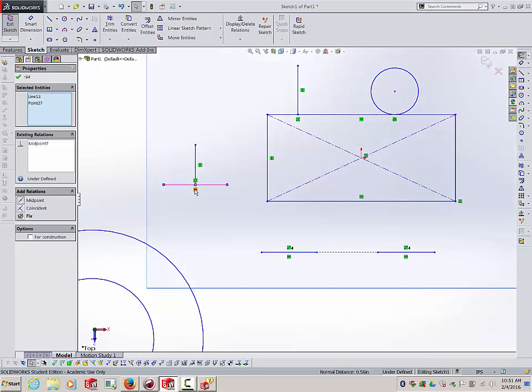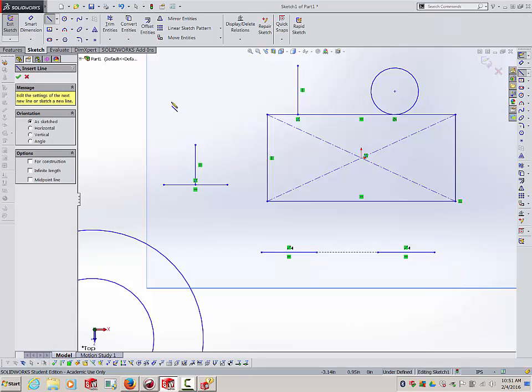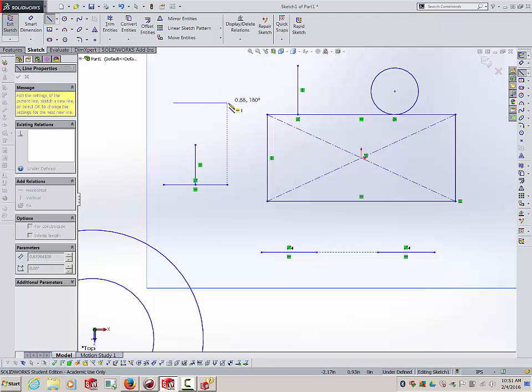And we also have the horizontal and the vertical that was kind of automatically put in there because I woke up those relations as I was building this. So as you go forward, you'll notice that these relations, almost like snaps, are being woken up, and you can see them being generated.